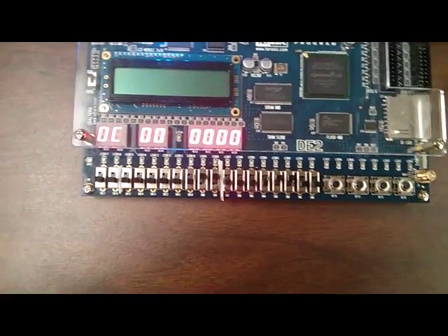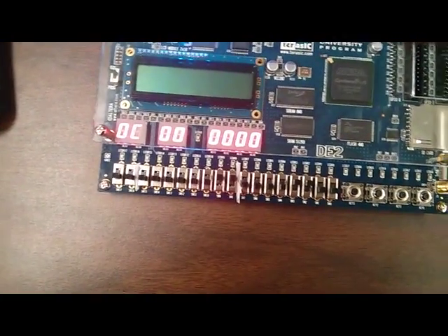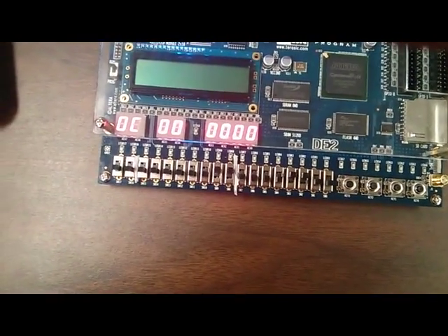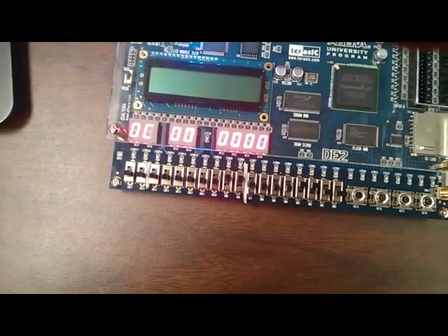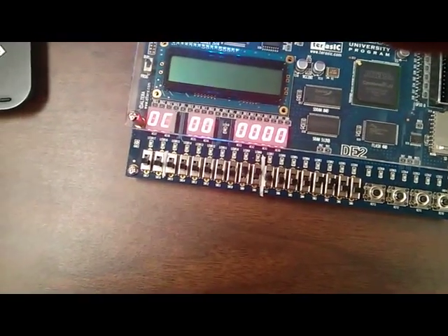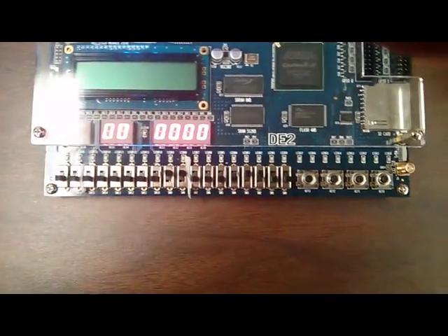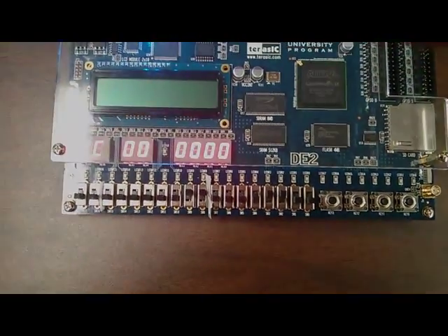both R and I-type instructions. R-type instructions take two registers, which are a form of memory, perform a binary operation on these two registers, then place their output in another register. I-type instructions take a number that's stored directly in an instruction, which is called an immediate, and perform an operation on registers using that immediate.